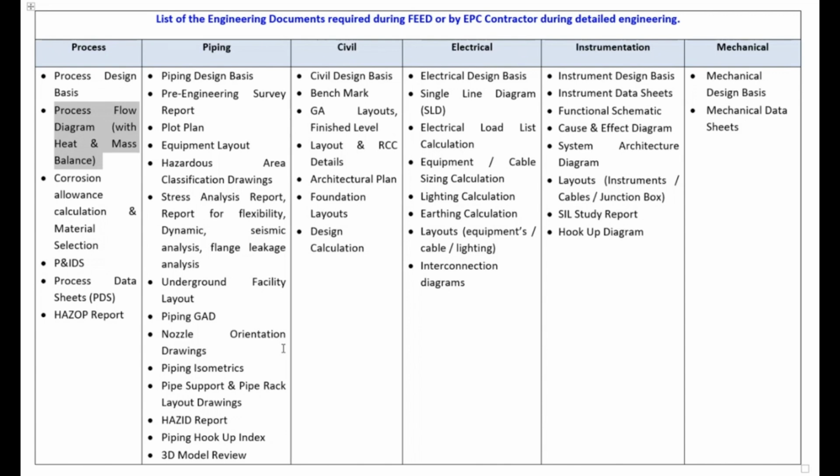In that, how much will be the gas? How much will be water? How much will be oil? And where will they be going? What will be the material balance? What pressure and temperature conditions will be there for production? That becomes the first driver for starting the total overall process design of the particular plant.